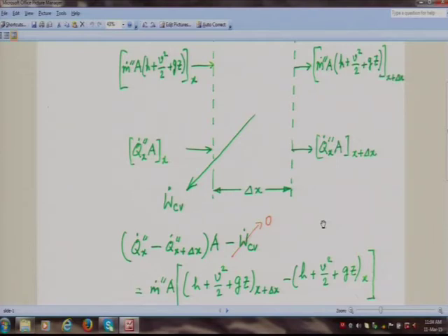Now, the slice that you see, slice of thickness delta x, this is in the domain, and in the domain there are temperature variations, for example, because we have a flame, and since we have a flame, there is high temperature in the flame region, in the unburnt region there is low temperature. So, there is a variation of temperature with x. We are talking about only one spatial coordinate now, that is x. So, that delta x is some zone in x. Remember, again we are doing a 1D problem. So, the heat flux term is q dot x double prime. We are writing it with subscript x because the heat flux is actually in the x direction.